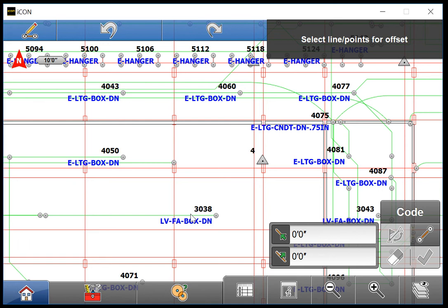To get around this, use your tape measure to measure an offset from the intersection snapped in chalk line on the deck. You'll want to make a mark directly on the chalk line as far from the intersection as possible. Bear in mind that you still need to use proper survey fundamentals when creating your offset and setting up your total station. Please see video 16, Setup and Survey Fundamentals for review, or contact me directly if you have any questions.